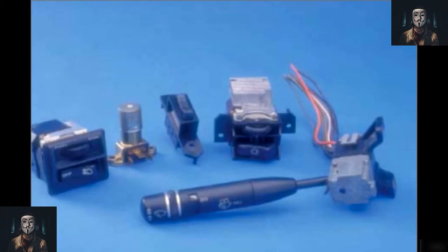One of the most complex switches is the ganged switch. This type of switch is commonly used as an ignition switch. In the following circuit, the 5 wipers are ganged together and the wheel moves them together. Battery voltage is applied to the switch from the starter relay terminal. When the ignition key is turned to the start position, all wipers move to the S position.